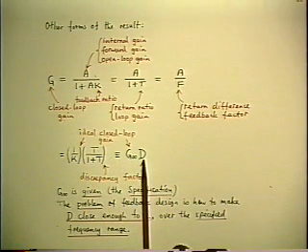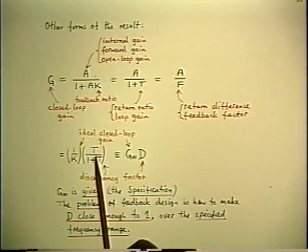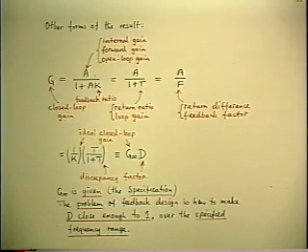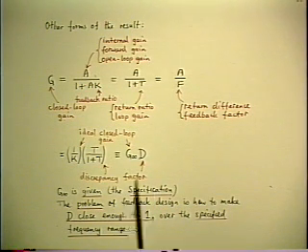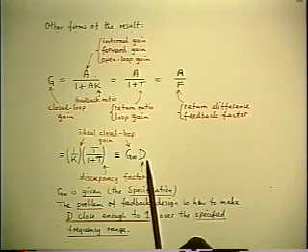Now, it's pretty easy to make D arbitrarily close to 1 by making t large enough, which is very easy to do, especially nowadays, because we have the ICs with umpteen dBs of gain. So that's easier than it used to be in Black's time, where you had to work with a minimum number of tubes that didn't have much gain anyway. So that's easy, but the hard part of it is the frequency response.